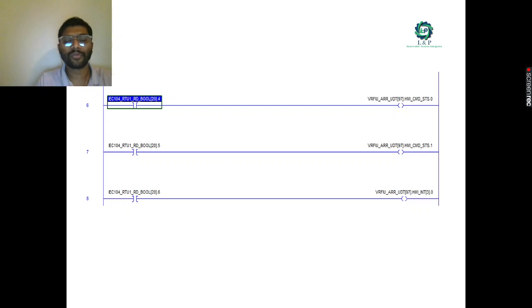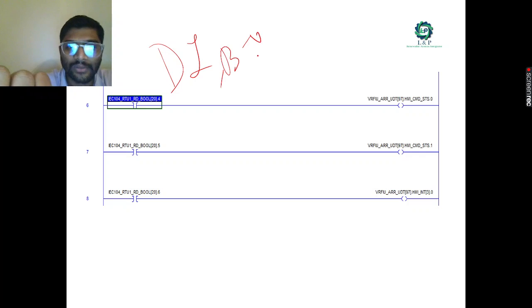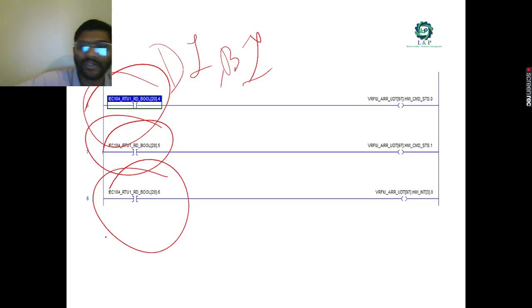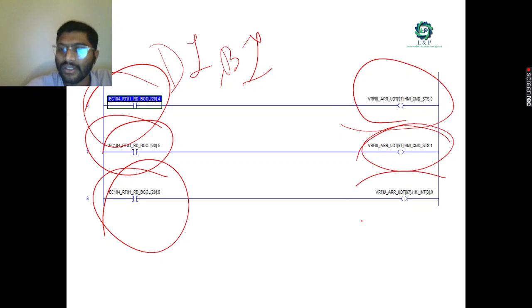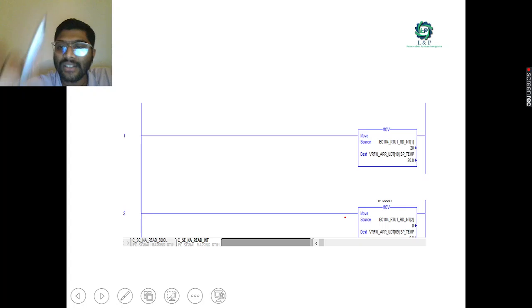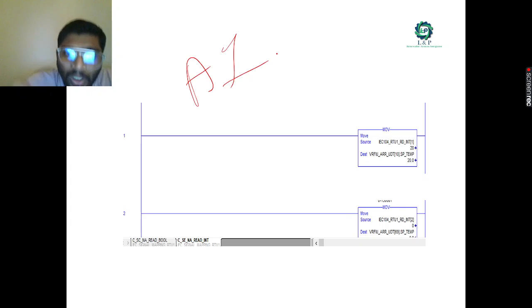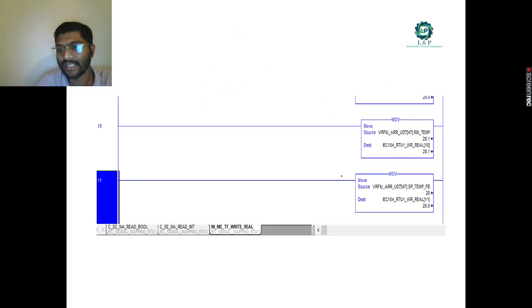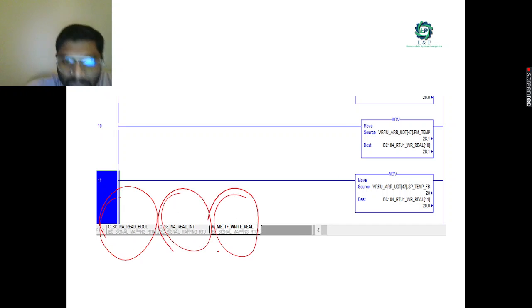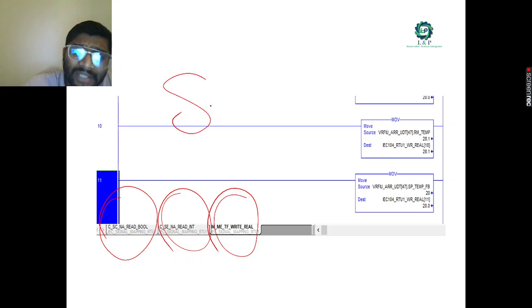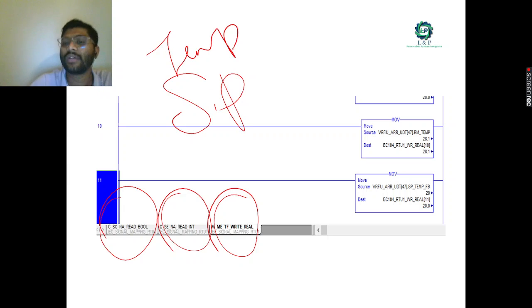As I told earlier, if you're going for digital inputs, okay, or the binary input values, so this is a basic one, boolean operation is sufficient, and once this is enabled through the proper communication, you can send this one to the concerned equipment. So on the SCADA, as you can see here, as I told earlier, if you're trying to read the analog input values, or it can be set point values, using the move block in your PLCs, you can move that value to the concerned equipments, concerned tags that you had created to the SCADA. Okay, so as you can see here, these are the reading operations, and this is the operation that you're going to write. So it can be for example a temperature set point that you want to assign, then you can assign it.